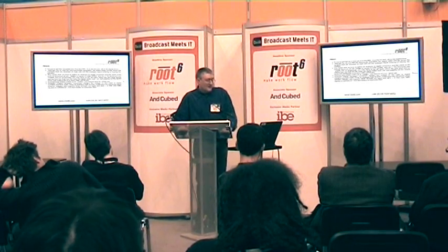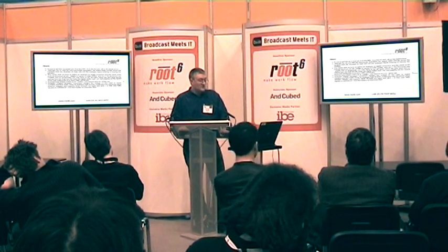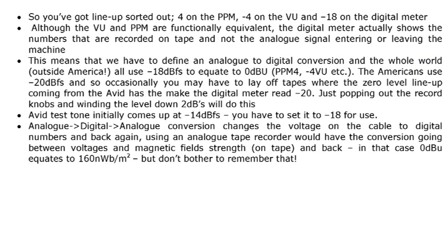So in terms of where you'll see and use those meters, the ppm is really the most useful. You do see fancier, modern digital meters, but really when it comes down to it, audio guys like ppms. And I've given you a bunch of figures as to how the scales on the different meters relate to each other. The 4 on the ppm, with the needle standing dead upright, vertical, is our line-up tone. On a VU meter, the line-up tone is at -4, because the VU meter has a different scale. And on the digital meter, as mentioned, the line-up tone is at -18.